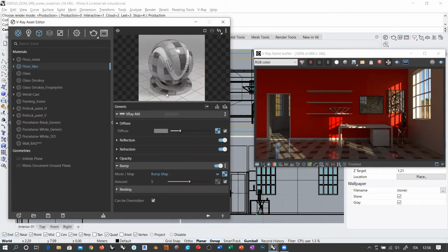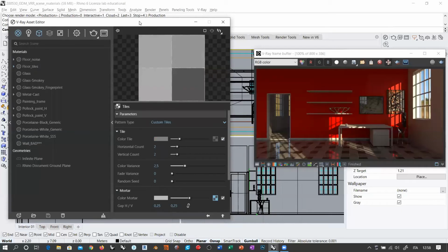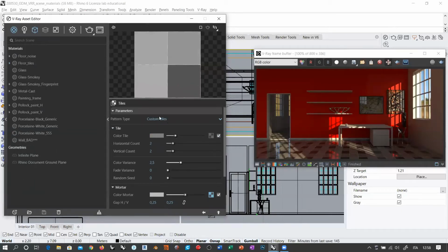Now what happens here? What happens is that we have created this kind of custom tiles with some color variants, okay? But we are allowing color variants only inside these 2x2 repetitions here. And so it means that this tile is going to be applied over and over and over because our mapping widget measures 50 by 50. So randomness is actually occurring in a region which is 50 by 50, which repeats itself several times. And so we have tiling, or a repetition of the same pattern over and over and over.